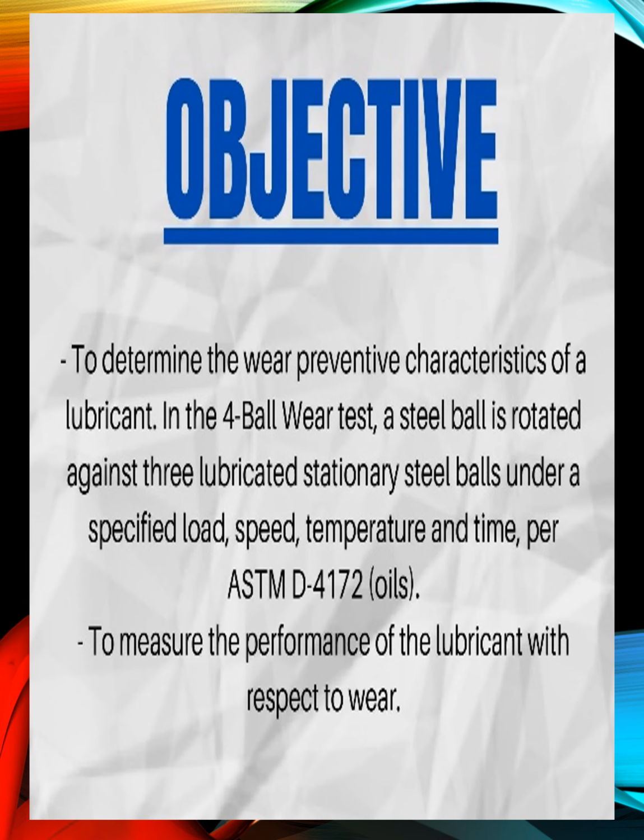The test is performed at fixed load, temperature and speed, unlike the extreme pressure test. After the test, the wear scar is measured using, for example, optical profilometry and can be used to judge the performance of a lubricant with respect to wear.